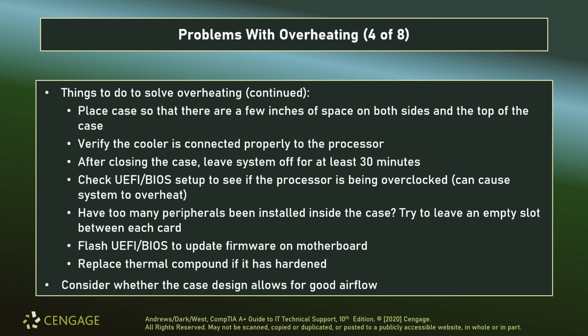Make sure the cooler is correctly secured to the processor. If the system is failing due to overheating, let's go ahead and unplug the system and leave it off for about 30 minutes. What I will usually do in that case is go ahead and take off the side panels, take out my compressed air or my anti-static vacuum, make sure everything is nice and clean, check my cable management, and just let it sit and air out for half an hour. Unplugged, completely unplugged.